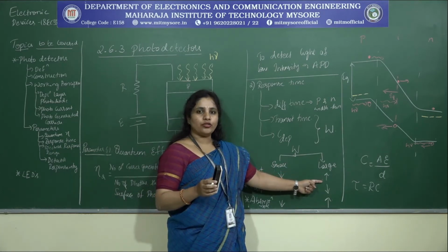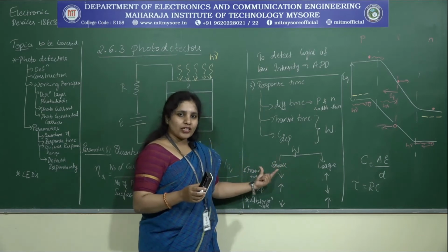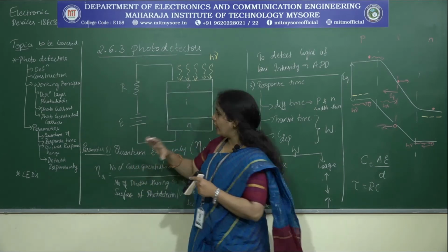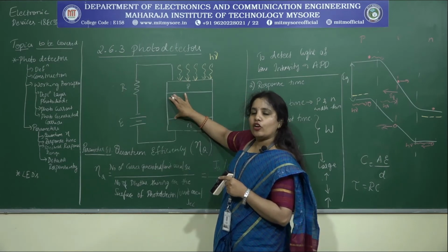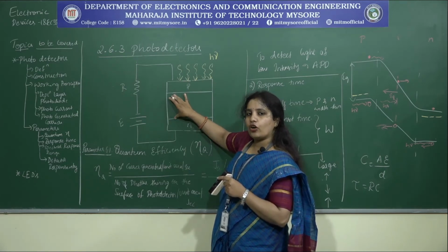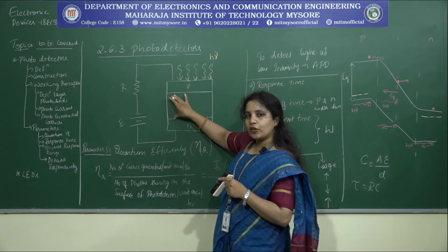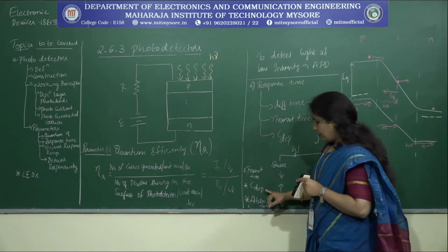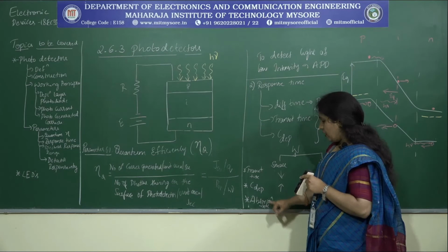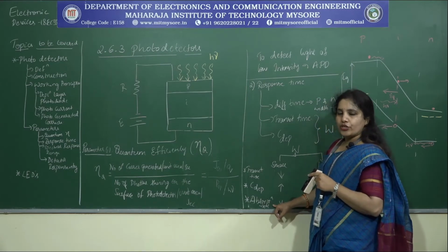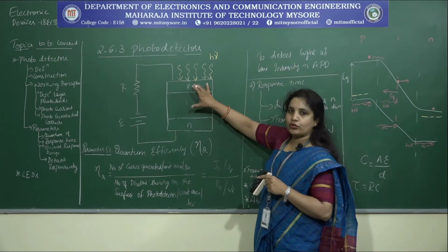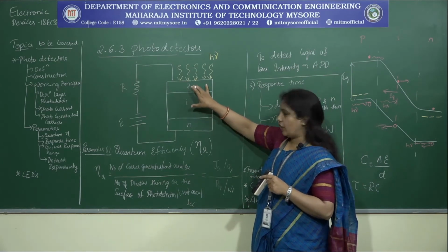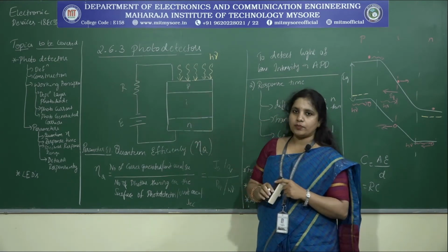Therefore, what you will try to do is, instead of keeping the width small, you will ensure that it is of a size wherein it makes a balance between the transit time, the depletion capacitance, and the absorption rate. Therefore I have kept it wider when compared to the P and the N regions.